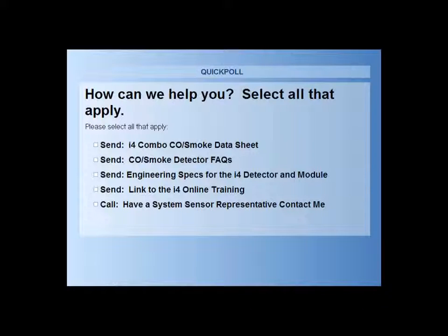Doug, they have a question on one of your slides. You talked about a smoke maintenance zone. So what defines a smoke maintenance zone? A smoke maintenance zone would be a zone on the panel that is set up or dedicated to receive just the maintenance or supervisory signals. In the case of a smoke maintenance zone, it could be a dirty detector. Our i3 series have freeze warnings, so that could be sent to that maintenance zone as well.